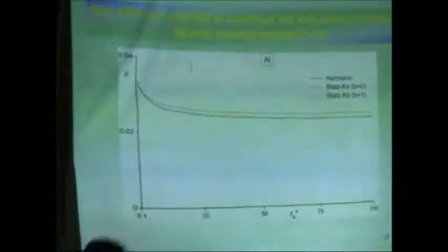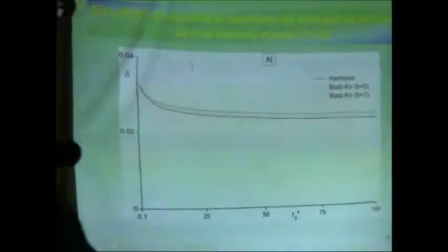And here we have a comparison of results for different models. Generally, the rods for the blades and core model are more stable, but with decrease in size, the difference becomes less and less apparent, which can be explained by the fact that for the nano-sized rods, the influence of the bulk material becomes less important, and a major role is played by the behavior of the surface.